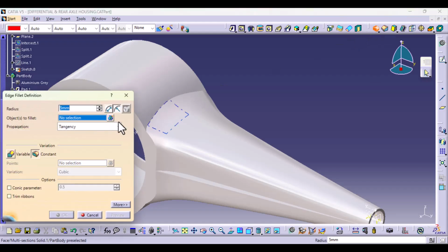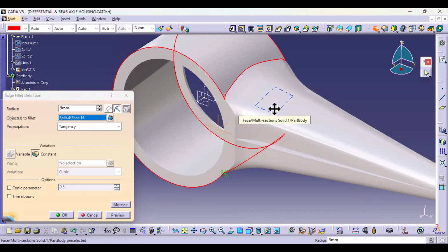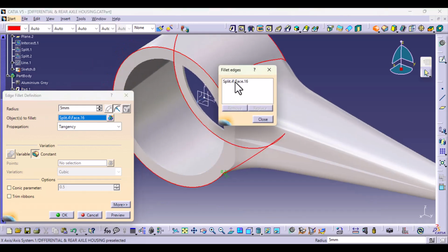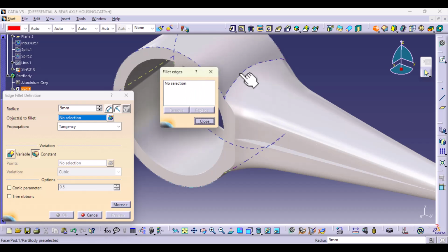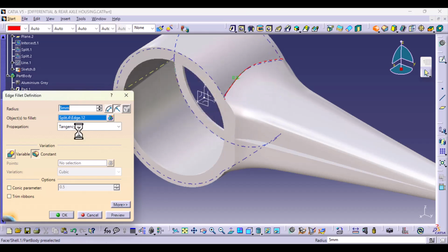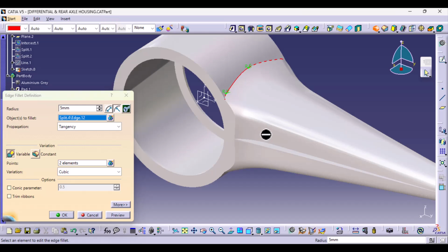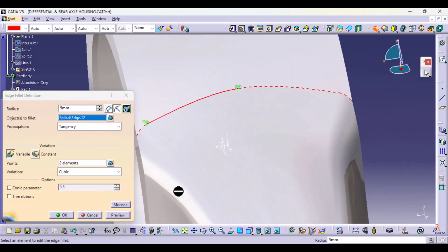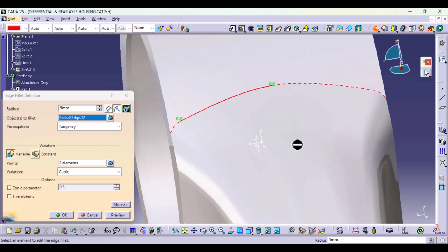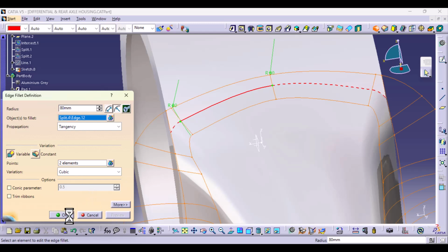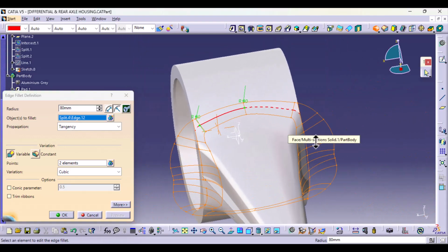Add a fillet. And because I want a large fillet, let me clear that. Remove, I just need the edge. I want about 100 millimeters. So I'm going to select variable, because 100 can only go so far. It cannot go towards the edges. For example, let me try, say 80. You can see the problem that we have.